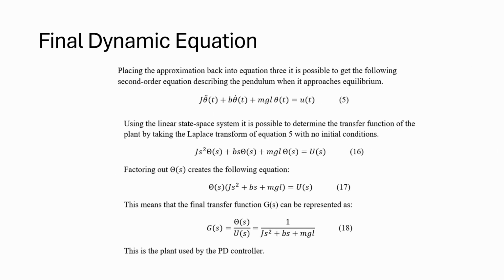For the dynamic equations, the goal of this was to simulate all of the torques about the system. So you have your torque from the pendulum inertia, your torque from the motor, and the torque from the weight of the pendulum. Rearranging this, and you get your input or the torque of the motor on the right. So that's U of t in this scenario. It was abridged for this presentation.